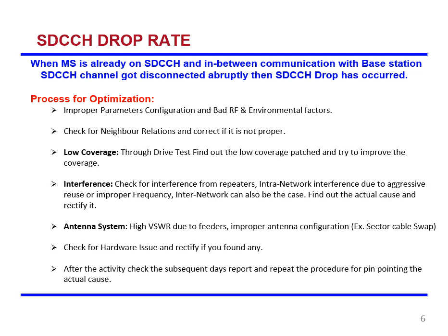Now SDCCH drop rate. SDCCH drop rate means whenever any mobile phone is already on SDCCH, and in between, the communication between the base station and the SDCCH channel gets disconnected, it is called SDCCH drop rate. SDCCH drop rate affects the location updations, as we have seen. SDCCH makes location updations, sets up the calls, and carries the SMS in the idle mode. All these features will be affected. So obviously you have to optimize that.